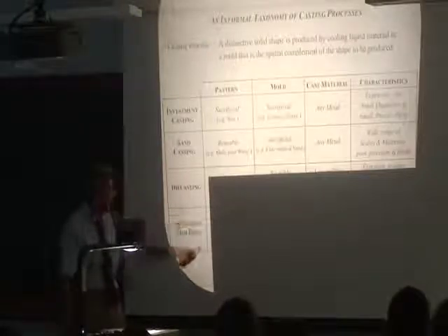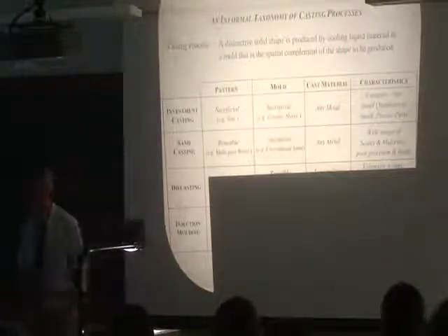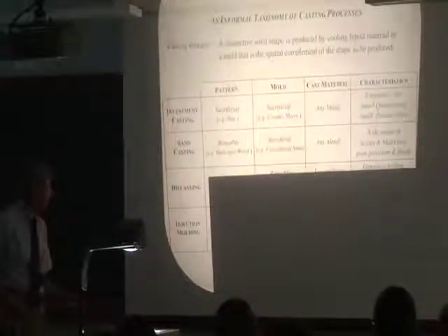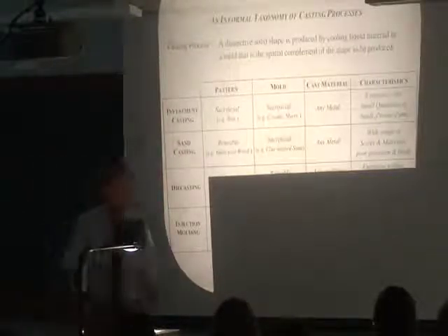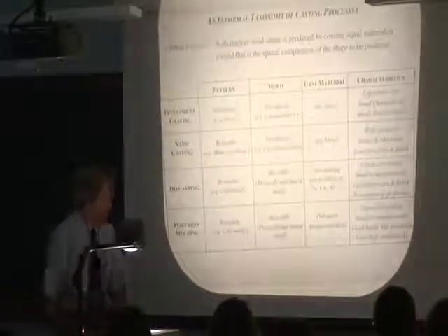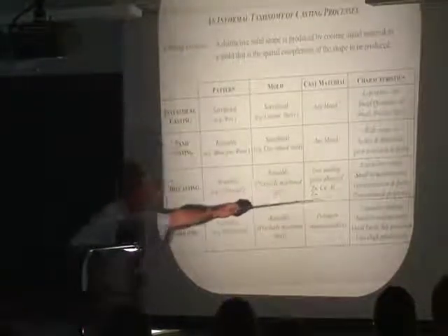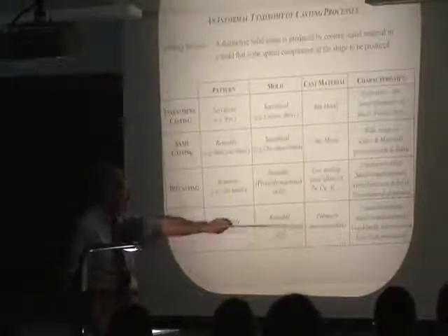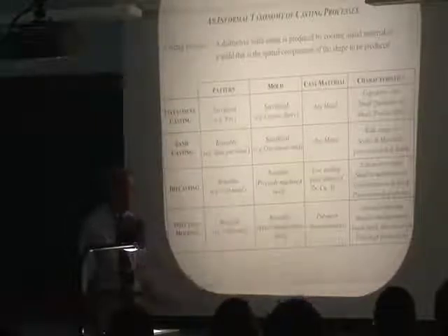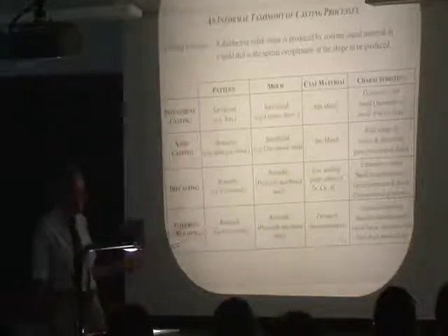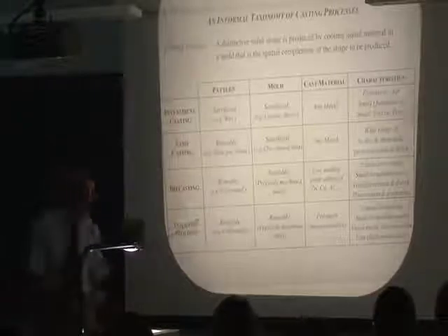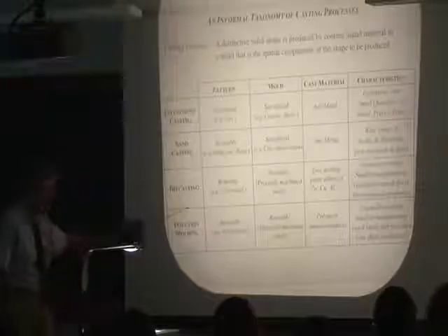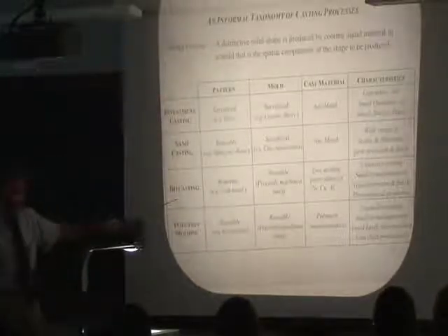Well, the other two use high precision metal dies. The dies are very expensive. This one, die casting, really is only suitable for low temperature alloys of zinc, copper, aluminum, tin, and so on. And the injection molding is for polymers, of which there's a great variety. But the machinery is similar, but works at different speeds and different temperature ranges. Very expensive dies. You don't want to use these to make 2 or 3 of something. You want to start with making 5 or 10,000.